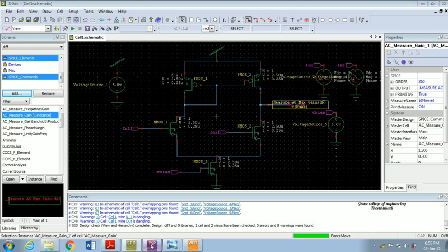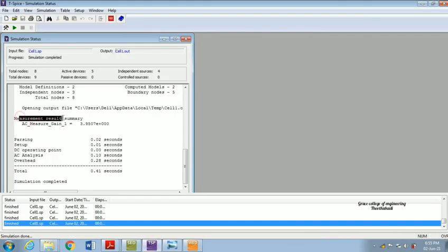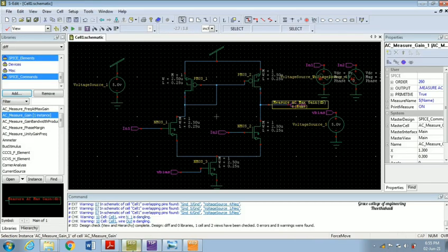So now you have to check the file, you see the gain value in our spice command. So this is the gain. So using the waveform also we can easily calculate the gain, and using the gain value you can calculate the CMRR value. So this is how we have to design and simulate 5 transistor differential amplifiers, and we have to check the verification operation using common mode as well as the differential mode, and later we have to perform AC analysis for both the circuits. So thank you.